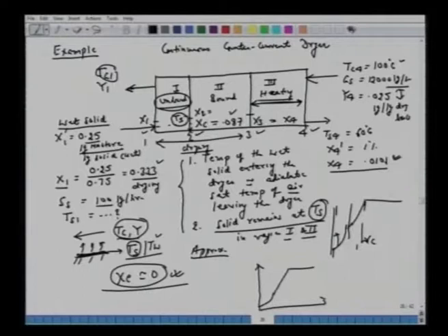The surface temperature of the solid, Ts, is not known here, here or here. All right, but we know the exit temperature, which is 60 degrees centigrade. That's the quality of our product. Let's look at the gas phase. Air humidity is known and air temperature is known. So nothing happens here, in the sense that there is no moisture evaporation from the solid. It's just heating. That means Y3, the humidity of the air at this interface between 3 and 4, will be the same as 0.034. So we know Y3. Y2 is not known to us, nor is Y1 known to us.